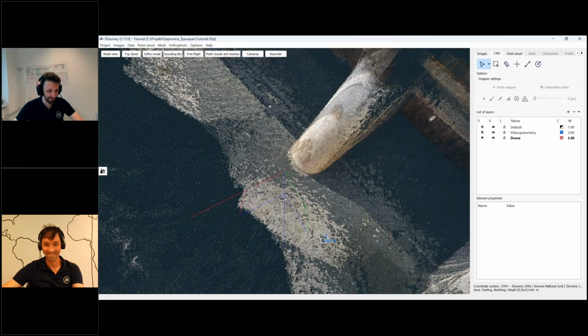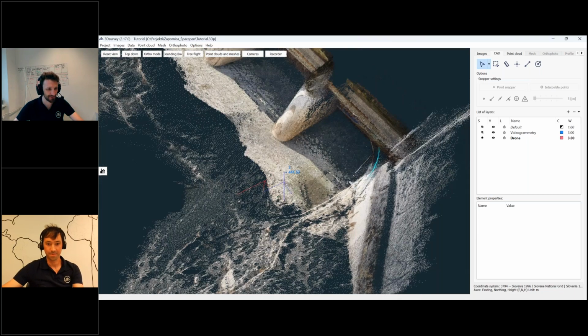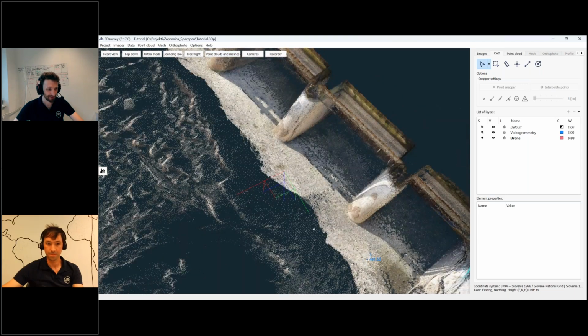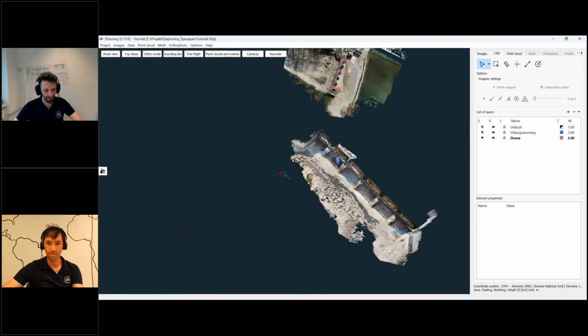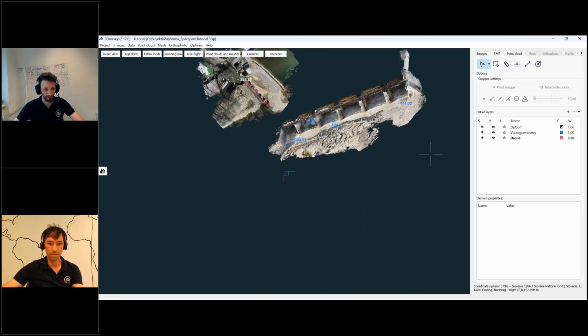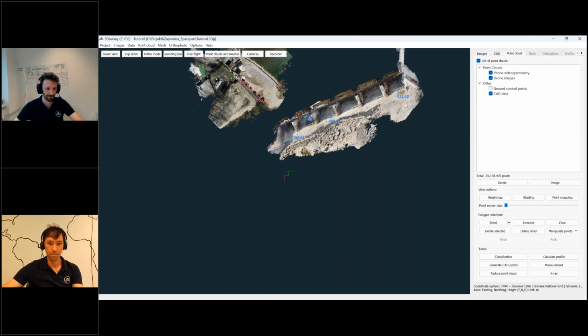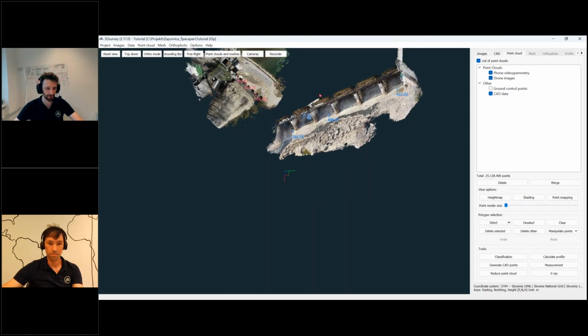And as you see, we have the same targets with the same names, marked by the same points. Well, points on a different layer. So now I want to transform this second point cloud onto this one. And I do this with a right click and choose transform.